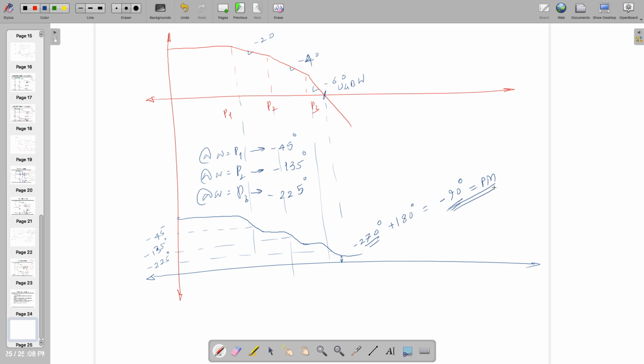So what is the key to make it positive? If you keep P3 outside UGBW, meaning much higher than this one. If P3 is here, then you know that pole 1 and 2 are inside.